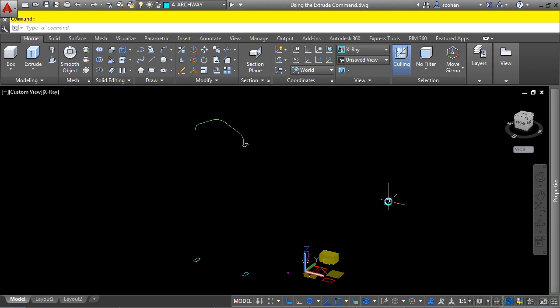You use the extrude command to create 3D models from geometry representing a 2D profile of that model. When you extrude a profile, a model is created at a specified distance and direction between the original planar profile and a projection of that profile. You create a solid model if you select a single closed loop object. If you select an open loop geometry or a closed loop composed of separate objects, you create a surface model.